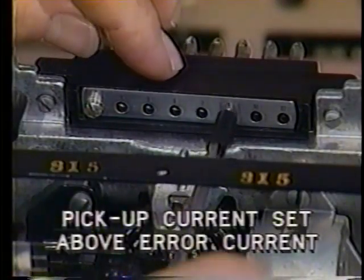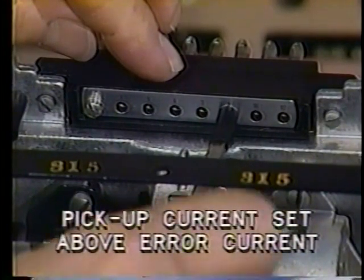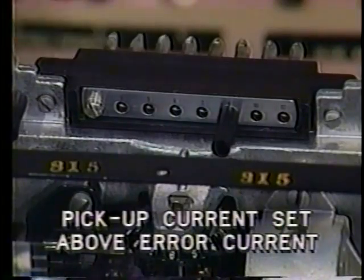The pickup current should be set so that it's above the estimated error current generated by the CTs for the through fault. This system is quite economical and is often used on low voltage buses, but you can see that it's slow and not very precise. More sophisticated arrangements are needed for protection of high voltage buses.